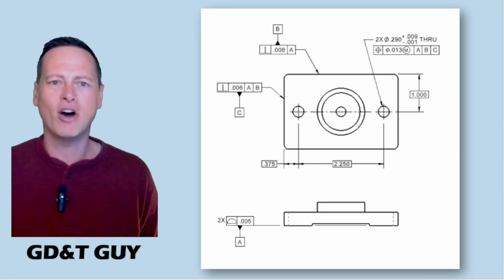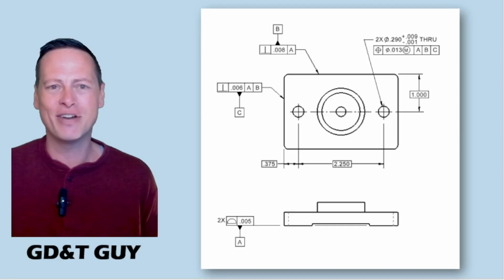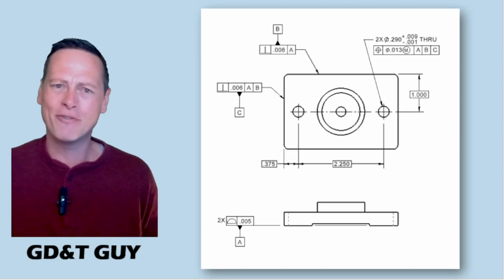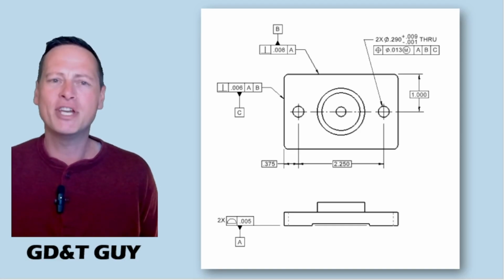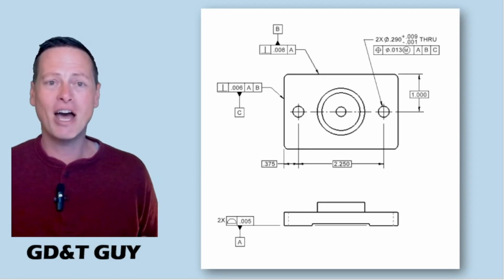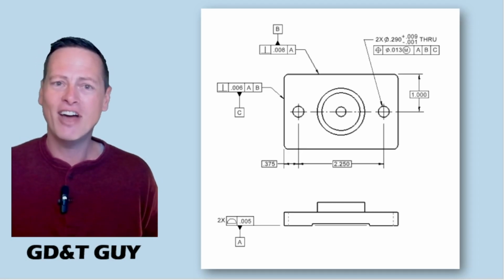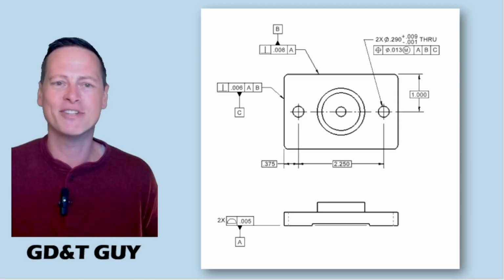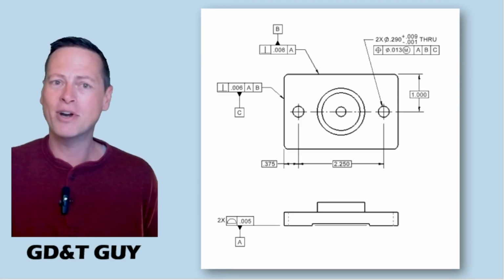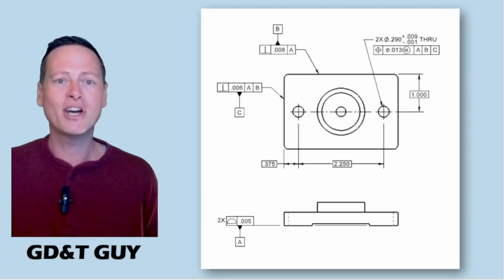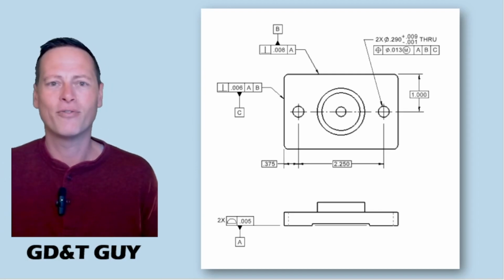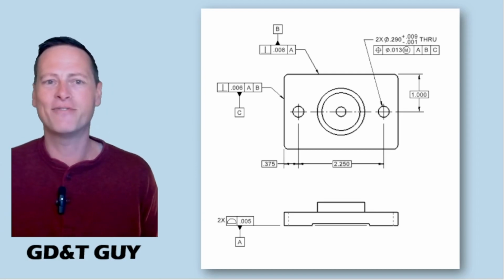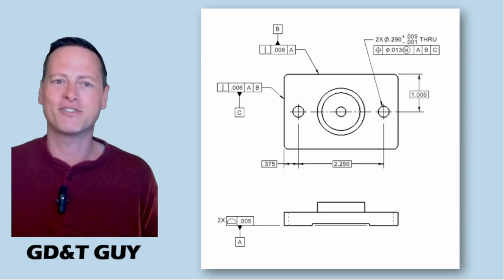So obviously we're going to call that my primary datum feature, A, and that's a 3 degree of freedom. I say 3 DOF, if that works for you, a 3 DOF constraint. And then look up top. Oh, this rectangle has a long edge. So that's obviously going to be a secondary datum feature, B, a 2 DOF constraint. And then it has this short edge, which is obviously going to be a tertiary datum feature, C, for 1 DOF, the 6th and final degree of freedom of a fully constrained part.